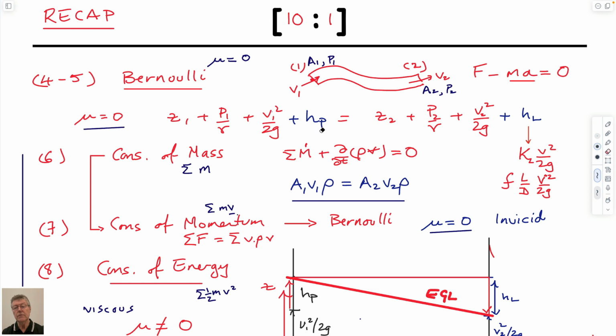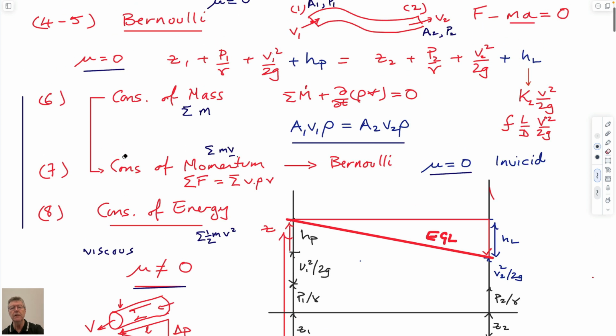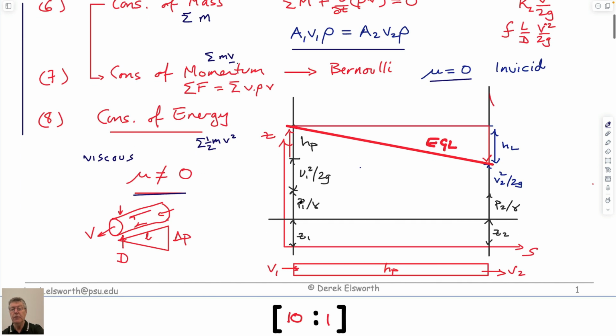And so we represent that in, you might remember we had two ways of writing this conservation of energy equation. One was with enthalpy included, so we could do some chemical calculations for hot steam going into a turbine and generating power. But the more usual one that we said we'd use more often would be just Bernoulli written for the case where it was no longer inviscid. And the case where it's no longer inviscid is where we have these head loss terms and pump head terms. And we can just describe those for a streamline as being Bernoulli.